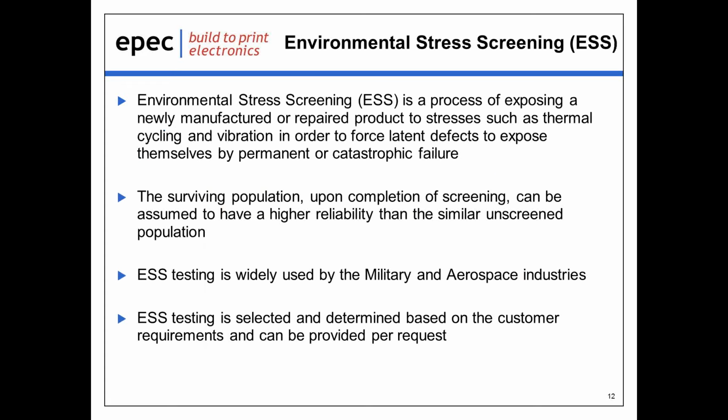Another test that we do offer is the environmental stress screening, or ESS testing. This is a process of exposing a newly manufactured or repaired product to stresses such as thermal cycling and vibration in order to force latent defects to expose themselves by permanent or catastrophic failure. And this is, again, done on the front end of the product.